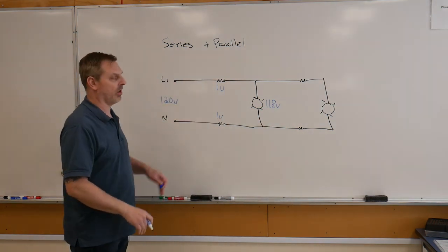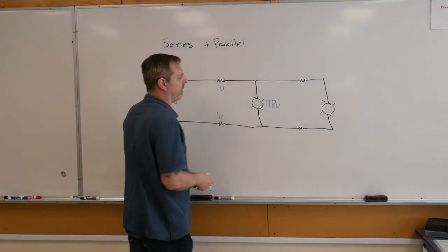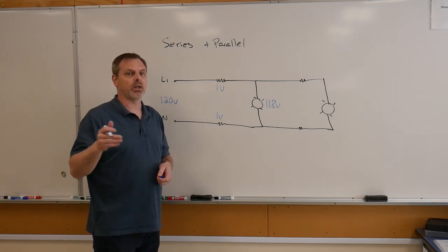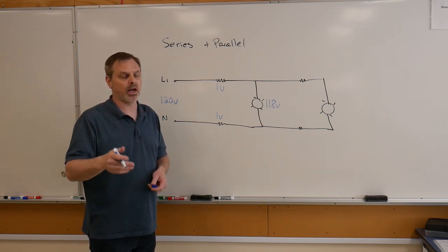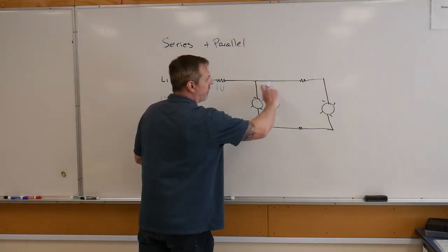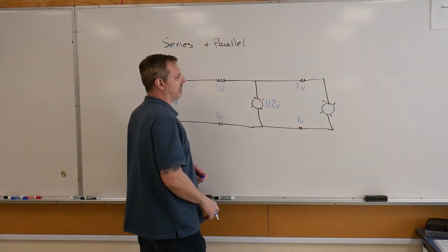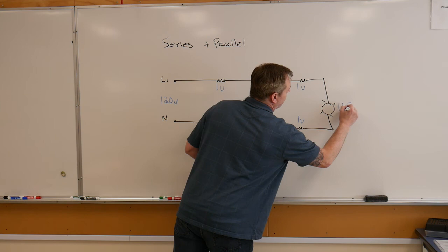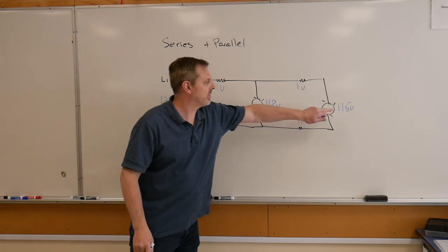We've learned that with voltage drop calculations. However, now you can see the cascading effect that we end up having, and that would account for why we end up having a voltage in our lab space at something much less than the 120 volts we would expect. Because we are the end result within the circuit in our lab space, our 118 here is now the source for this half of the circuit. And if we had a further 1 volt drop at each of these conductors based on the current that load was drawing, now we're down to 116 volts. How did I get that? 118, subtract the 1 volt, subtract that other volt, to give us the 116.